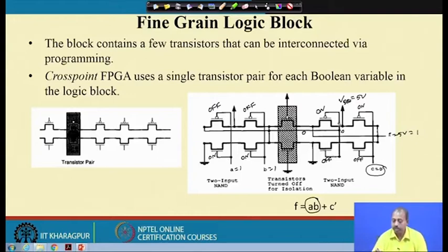So, you see that this transistor being on, this VDD that we have is available at this point, because this transistor is on. This drain and source will be at the same potential. Since the drain is at 5 volt, this source will also become 5 volt. As a result, this line will become equal to 1 again.